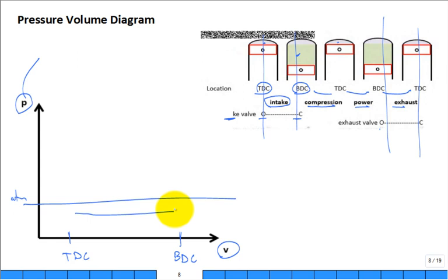Anyway, so it is under a state of vacuum, right? And if you have a vacuum leak, anybody had a vacuum leak on the intake manifold maybe? The gasket? Yeah, had to replace a few of them. Well, how do you normally check for a vacuum leak? You take a little spray can of flammable fluid and you spray it where you think there's a leak.